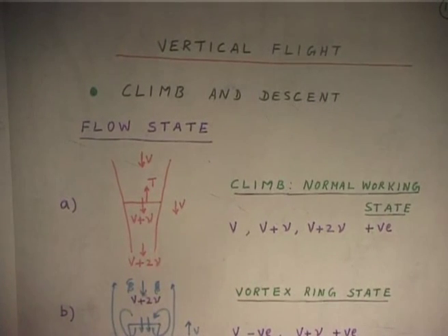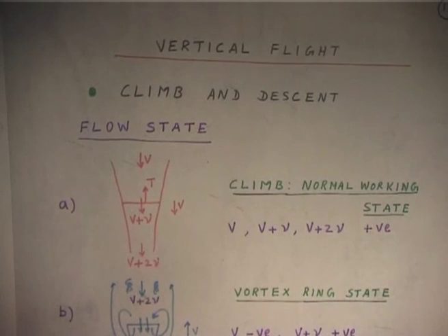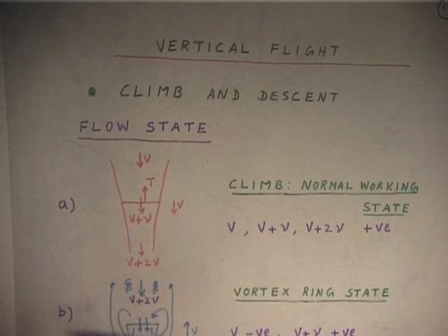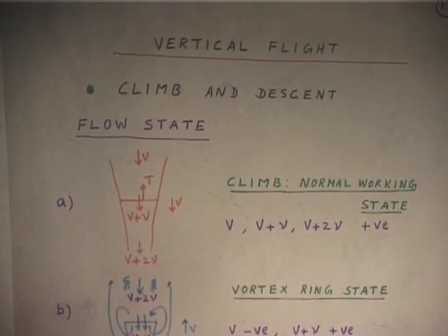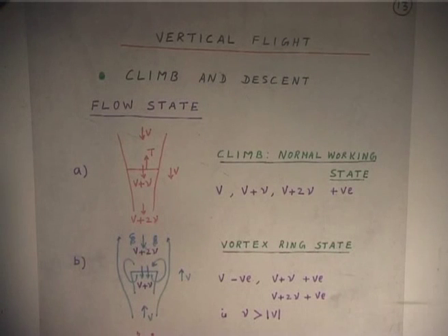If you are sitting on the rotor, what you will feel is the far field upstream. You will see the wind is coming with the velocity v, and everywhere, because you are moving, the wind is going down. This is outside the slipstream, velocity is also down, but the rotor is doing some work, and that is basically increasing your velocity; we will derive for this case also. Okay. At the rotor disc, now it is v plus nu, where nu is the induced velocity, v is the velocity due to the motion of the disc or the rotor, and then far field downstream.